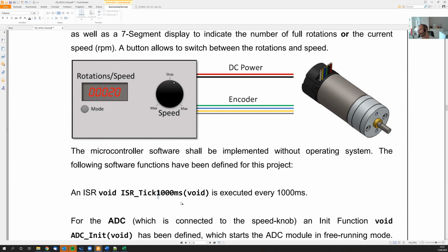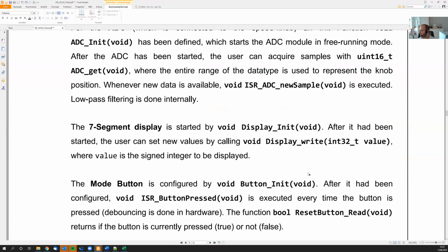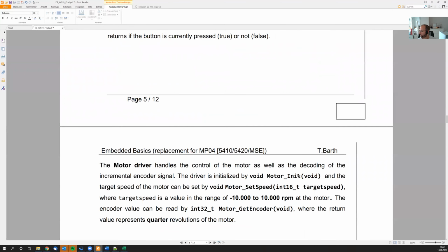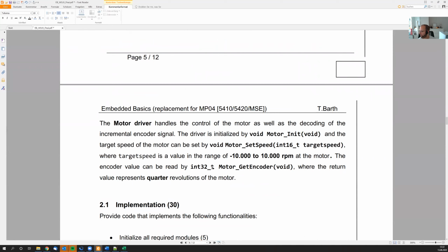Okay, so as I said, this was originally meant as the 1.0 question. So the idea here is we can buffer the old encoder value. Then every second we check for the new encoder value, and then we can calculate the speed from that. Is that clear?